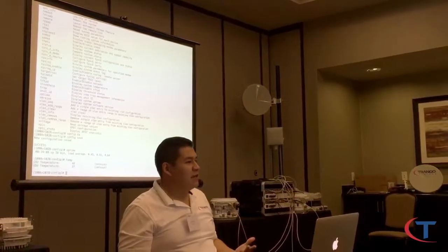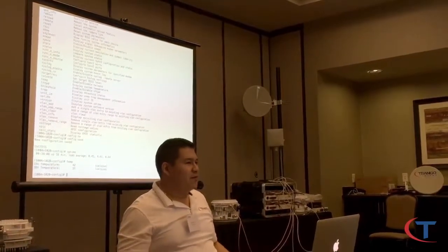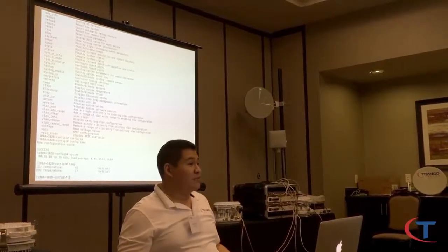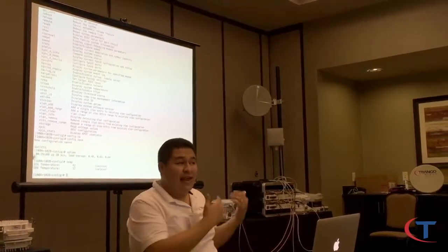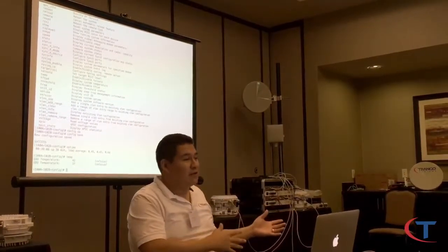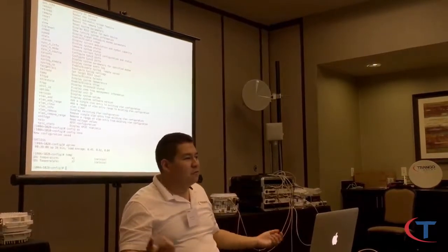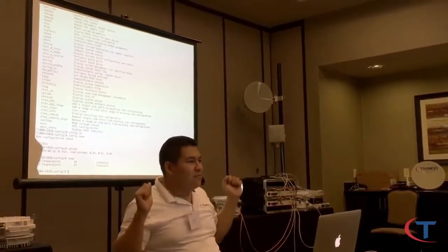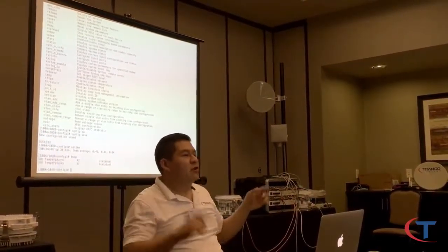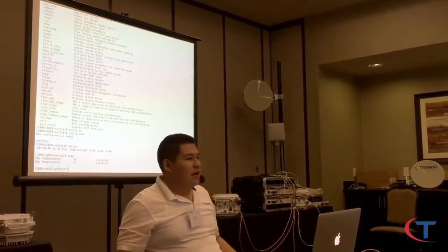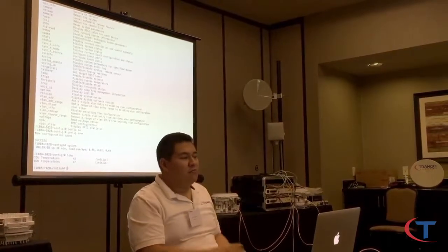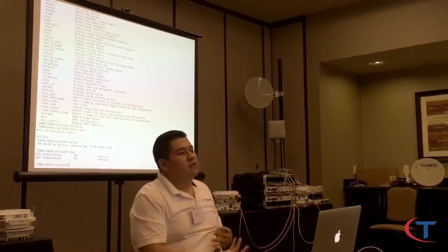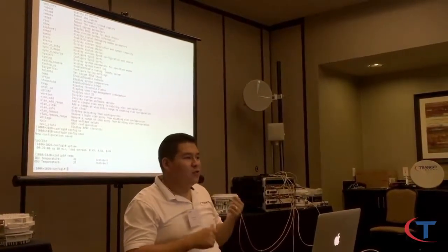That's what happens when we're troubleshooting with customers. A lot of times it's, well, my IF cable looks perfect. It may look perfect, but it has water on it. And firsthand, it happened to me on our towers out on Black Mountain. If you look at the IF cable, it looks normal. I mean, bone dry. But if I take it out, nothing works. So I replace the cable run, I put the old ODU back on there, no problem. So just to share the story, the IF cable has a lot to do with split systems.